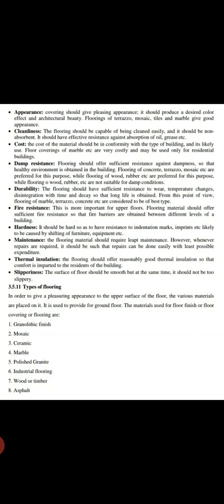Hardness. It should be hard so as to have resistance to indentation marks, imprints etc. likely to be caused by the shifting of furniture, equipment etc. Maintenance. The flooring material should require little maintenance. However, whenever repairs are required, it should be such that repair can be done easily with the least possible expenditure. Thermal insulation. The flooring should offer reasonably good thermal insulation so that comfort is imparted to the residents of the building.